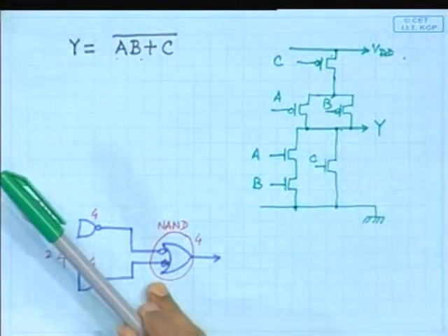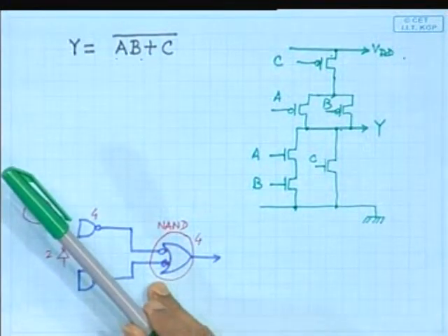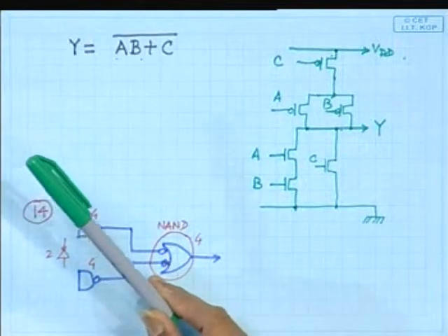That typically happens when you are designing an adder, because addition is an ubiquitous operation. Whether it is multiplication, square root or anything else, you are using something like that, so a few less transistors. Suppose in your design there are 10,000 multipliers or 10,000 adders. If you can save just 2 transistors, then it will be multiplied by that factor.